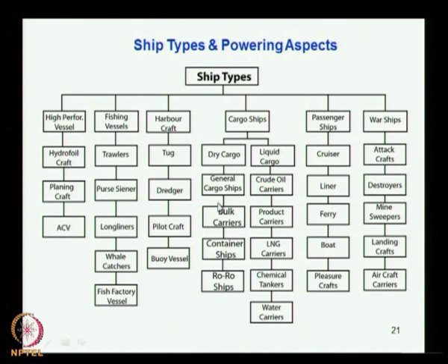For a general cargo vessel, which normally operates as a conventional vessel, as with all these vessels we discuss here, majorly 4 operating conditions are considered. That is, you consider the fully loaded departure condition, fully loaded arrival condition, then ballast departure and ballast arrival condition. These are the 4 conditions. So the fully loaded departure condition is the one with the maximum displacement.